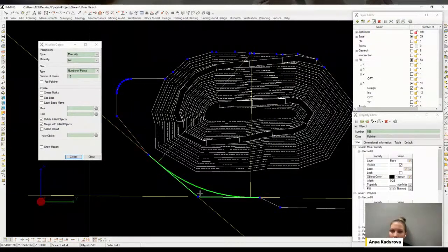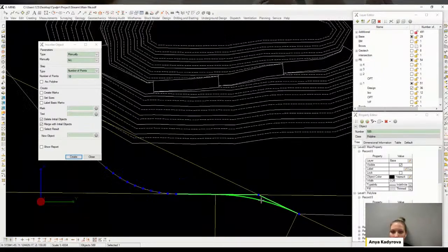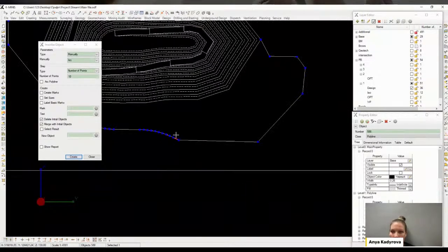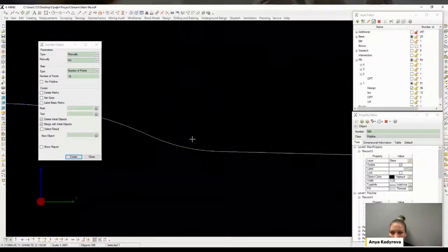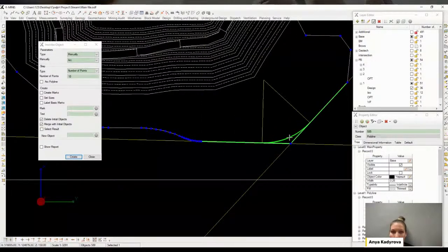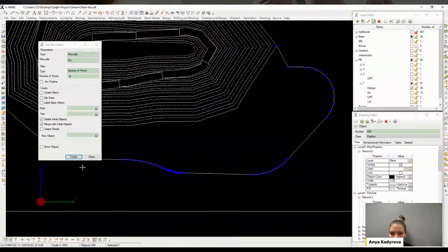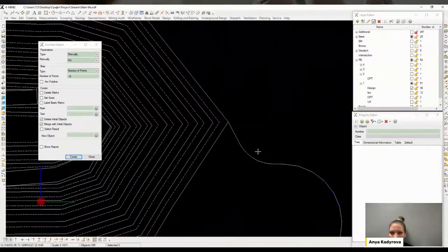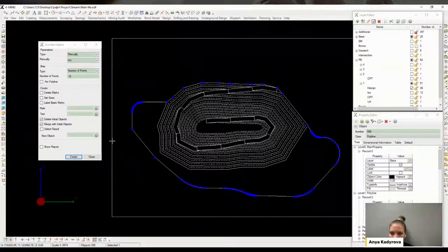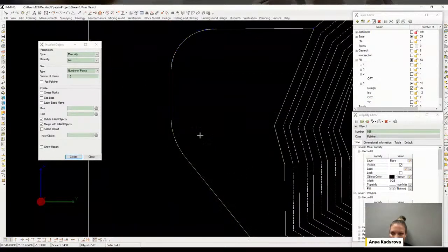So let's build the edges and proceed to the construction of the exit part. In order to make a viable pushback project, it's necessary to repeat the configuration of the previous pushback in a place where mining will not be performed. Let's add the road with the same parameters and in the same place as the previous pushback.